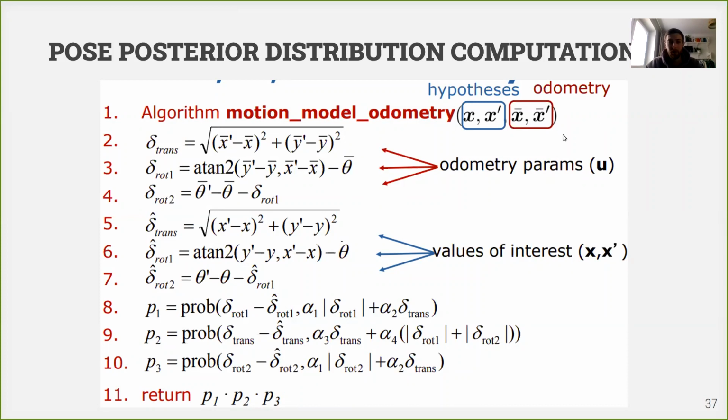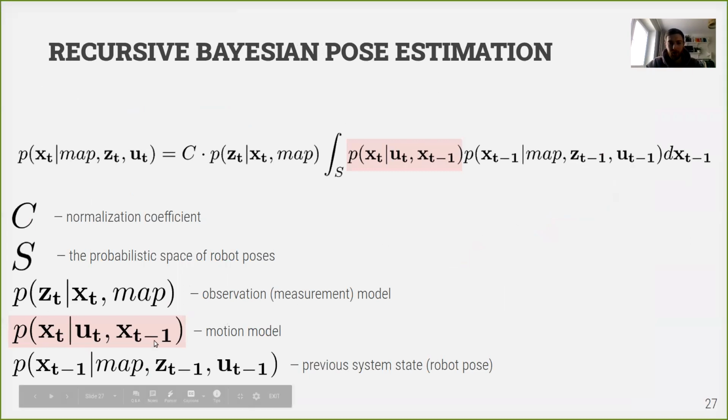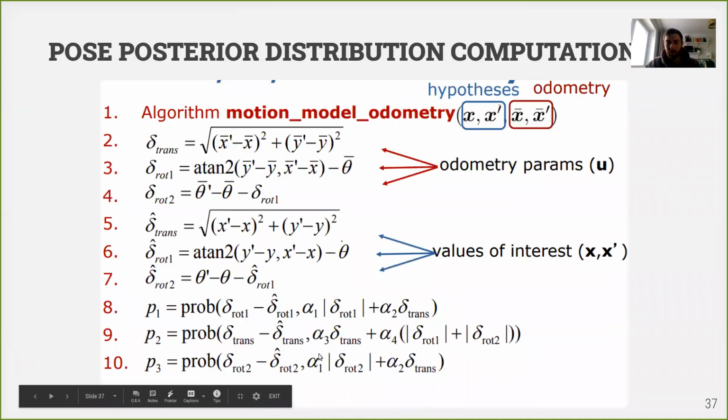And this function is actually something representing this motion model. You see, we have our previous state and control signals, and for any given place in the world, we can answer the question of how probable it is that, given the previous state and motion parameters, we ended up in this place. So this is the first type of motion model, the probabilistic one.